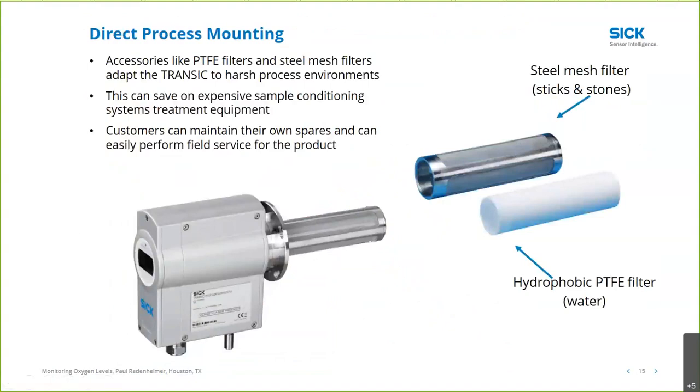Sometimes when you're making an in situ measurement, there can be undesirable materials in the sample flow. Sticks and stones, or water as I refer to them, can be present in almost any process. So we provide either a screened mesh or a hydrophobic PTFE filter, Teflon filter, in addition to the screen mesh to repel water and solids that may be entrained in the process flow.